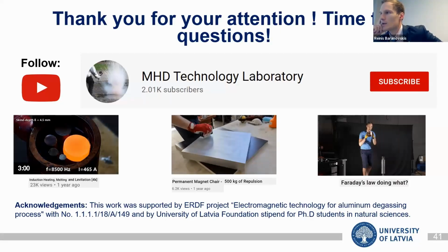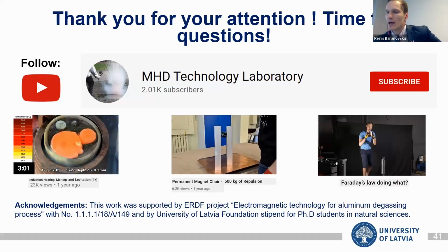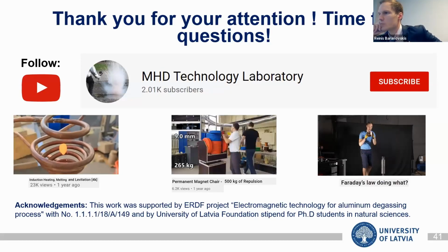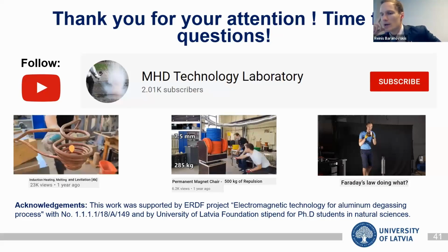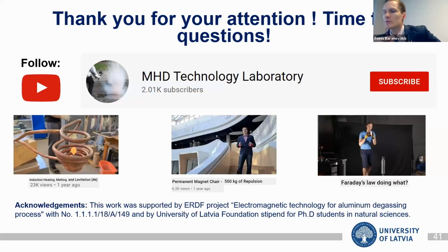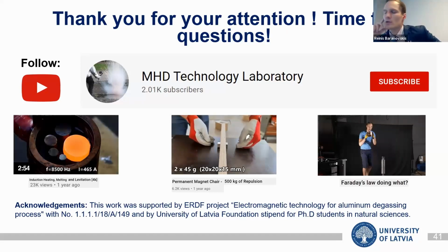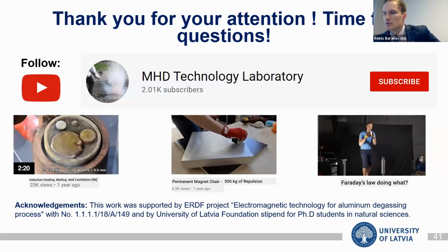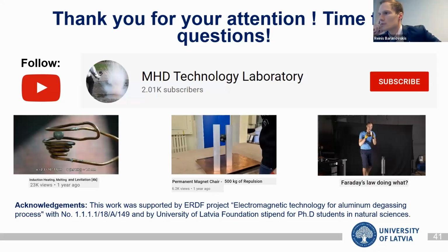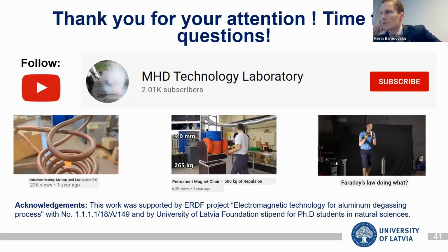So I don't see any danger. It is true that the load changes when we don't have it or have less of a material. It's also quite important in our stirring applications, where it's really difficult to stir a half-empty container or to heat a really small object in the same inductor, simply because the induced electrical currents are too little. But in these cases, there is no danger when it's not loaded.